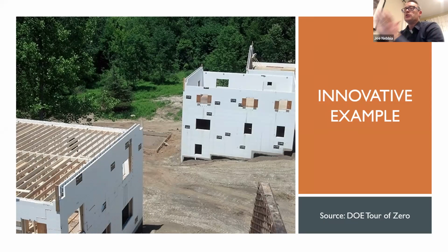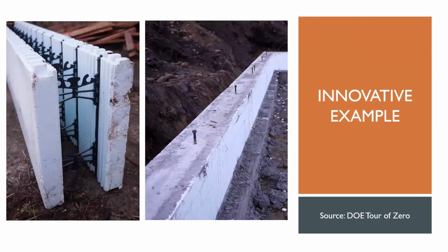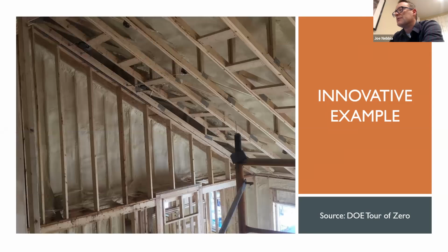So this is 2 panels of rigid foam, and as they build it with the blocks on site, they pour in the concrete, and it forms a super airtight as well as super structurally sound wall, very high wind ratings and that sort of thing. Absolutely. And well insulated. Right. This is another picture of an ICF close up. You can see where they would pour in that concrete.